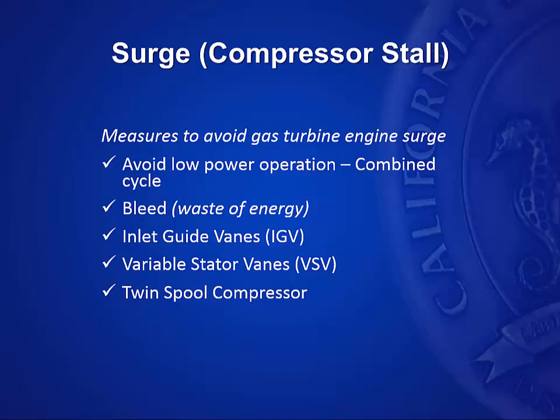Then behind that, as you work down, you can have variable stator vanes. Each one of these stator vanes can be manufactured so that you have an adjustment arm, and we'll go into that and show you how this is done. I can rotate each one of those vanes around the whole circumference of this engine in that compressor section.